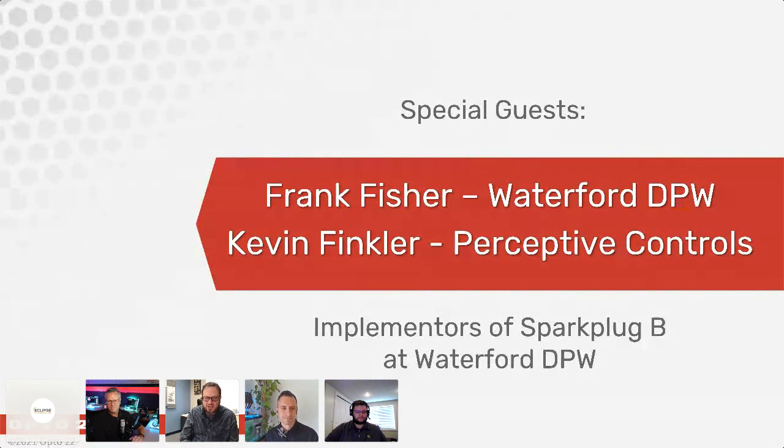So we're just beginning that journey. And just to give you a quick update, we've got 90 sites total. Our complete sewer system is completely done. We're at 68 sewer lift stations that are now on MQTT. On the water side, there's more programming and config, and we're about halfway done with that. So we're looking by the end of 2022 to be completely onto MQTT with our whole infrastructure.